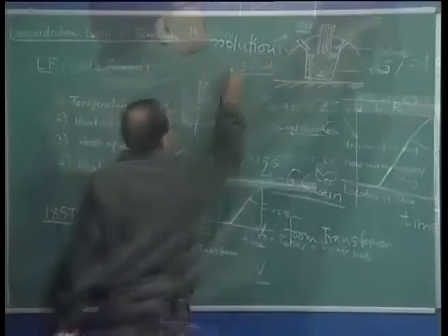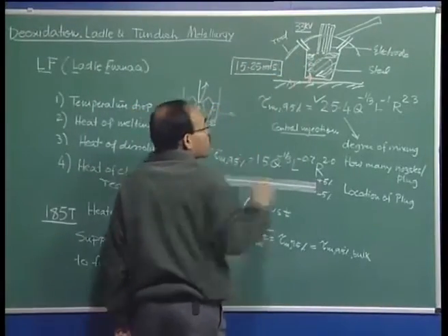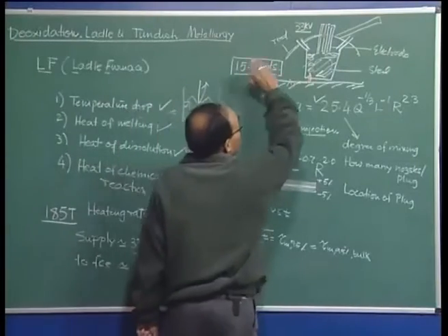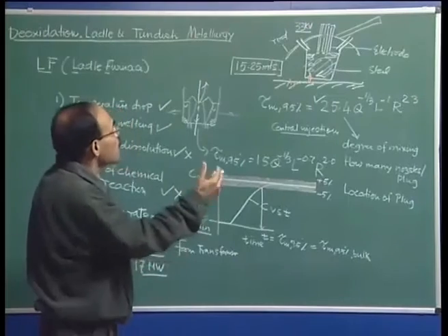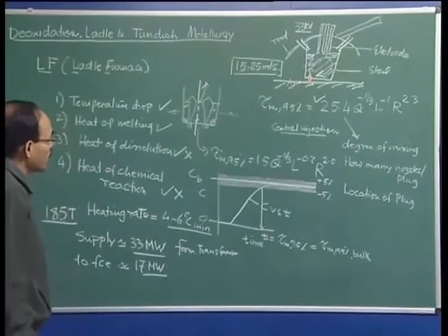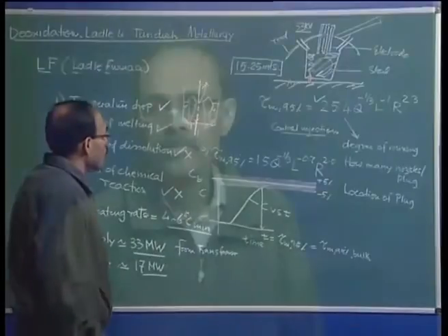The entire processing is done for 25 minutes, where we may have aluminum wire injection into the system for deoxidation. We may be adding some amount of alloying additions to melt and adjust the composition of the bulk steel, and so on.